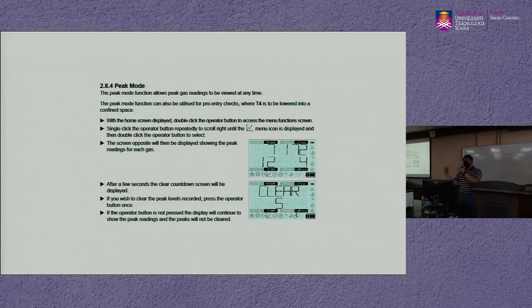If, for example, we use a gas analyzer, it will do a manual air zero in ambient air, where it sucks in the ambient air outside and purges our sensors, bringing the reading back to empty as per its specifications. So it means that if we do not do the zeroing properly, it will start its baseline with that reading already there. For example, if we do the zeroing at a site that already has a CO level of 10 ppm, it will detect that, and the zeroing is done under the condition of 10 ppm of CO. So once we enter the site, it will start at 10 ppm, not at zero.